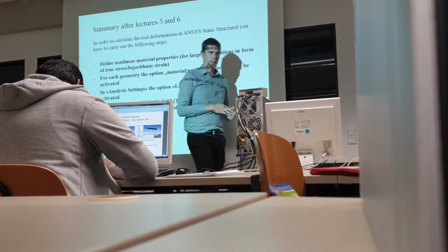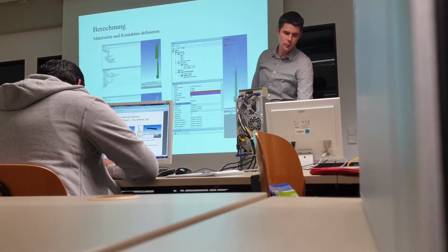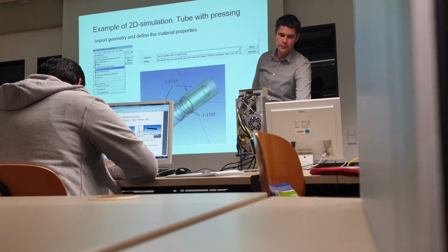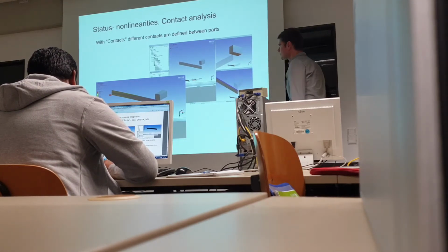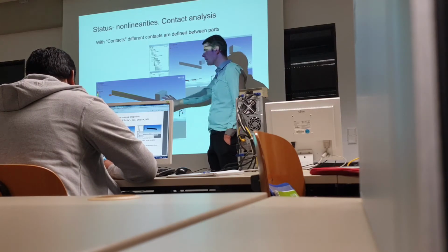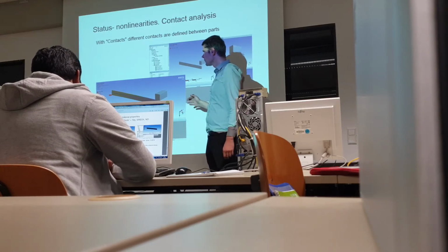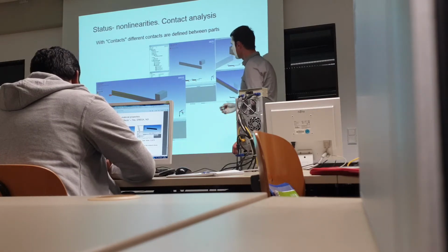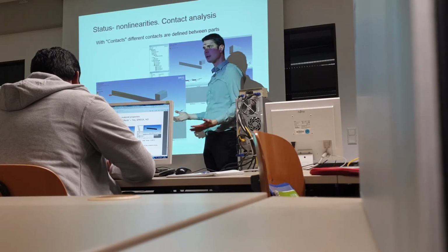So the last point, what we have: nonlinearity in contact. Now our main task for today is to calculate this situation, a 200 Newton force with contact. For example, what I did now, 100 or 200 Newton together, 100 on a half model. This task always appears in simulation. For example, the customer told us we have a 200 Newton load force now. The question is how much is the stress?